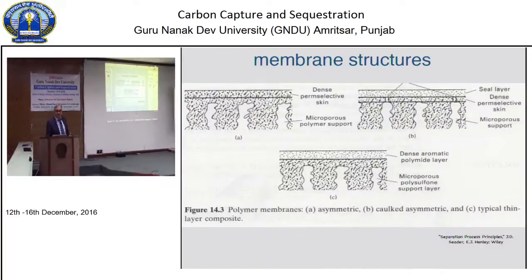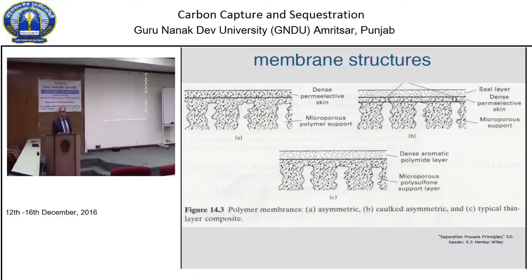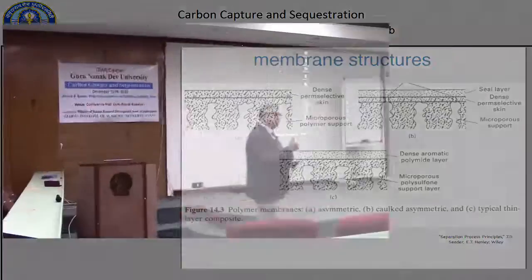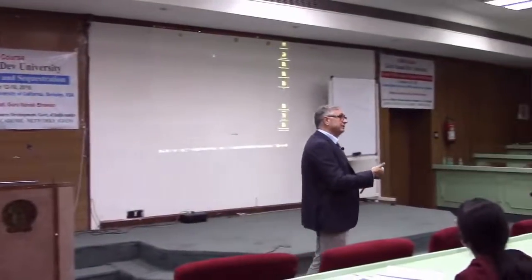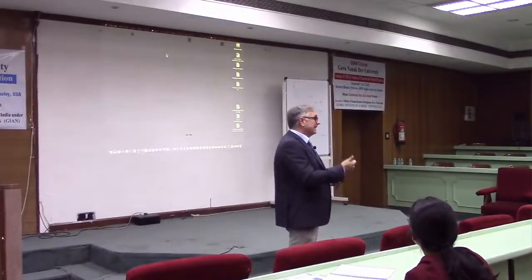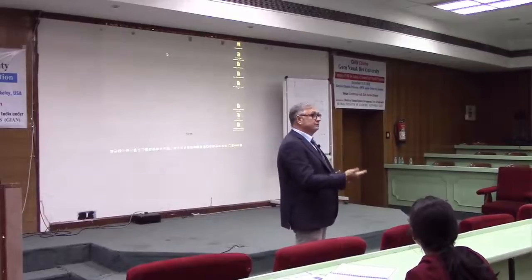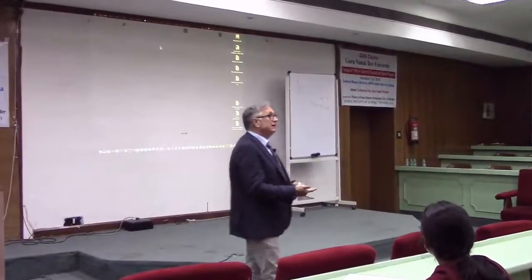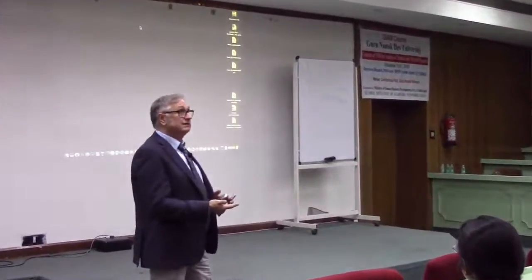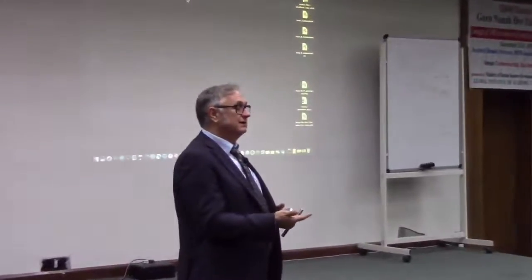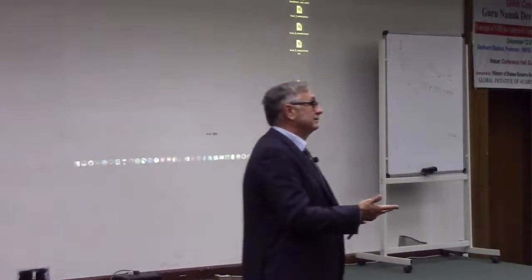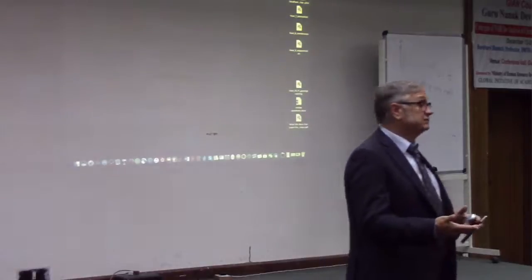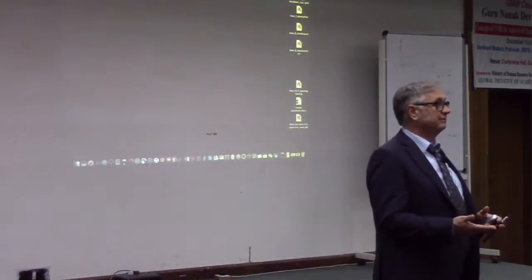So what I've tried to show you so far is that carbon capture can happen in three ways. Absorption into a liquid, off the shelf, ready to go. Adsorption onto a powder, opportunities for materials research not yet ready to deliver, at least for coal-fired power plant. And then membrane science has delivered really astounding engineering breakthroughs and is nearly ready to go.